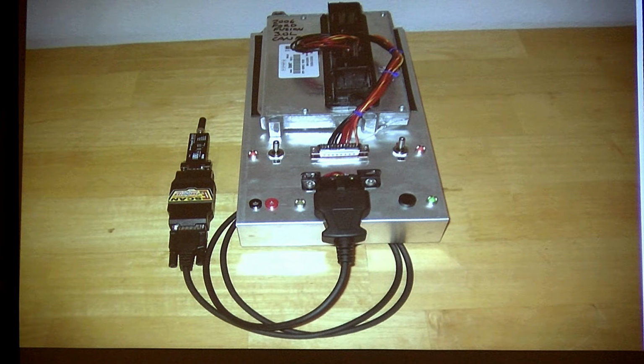Drive-by-wire cars all have 2 5-volt systems in them. Because it's drive-by-wire, I need a safety-critical system, so I supply the APPS, the accelerator pedal position sensor, with a 5-volt regulator that is isolated for one of the circuits, and it's isolated totally from the other circuit. Grounds are isolated, signals are isolated. It's a safety-critical system. That's customer intent, driver intent.